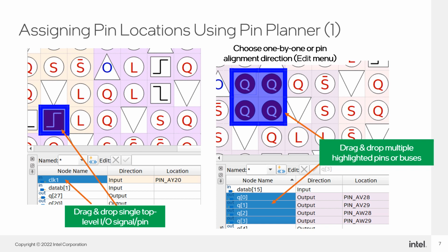If you drag a group from the Groups list or a selection of multiple signals from the All Pins list, you can decide how to place the signals in the package view using buttons in the toolbar and options in the Edit menu. The default option is to assign the multiple signals one by one. After you assign the first signal, the next selected signal becomes attached to the cursor, allowing you to click in any location to create its assignment. This continues until all selected signals are assigned. Press the Escape key at any time to cancel.